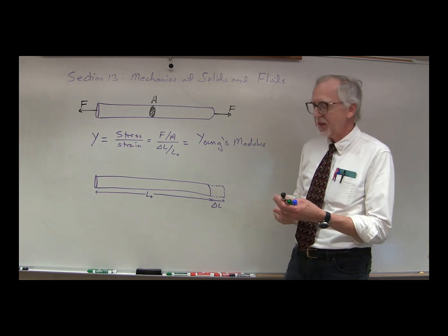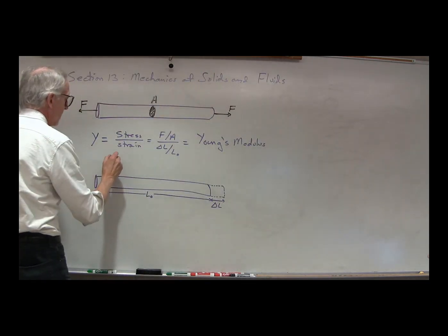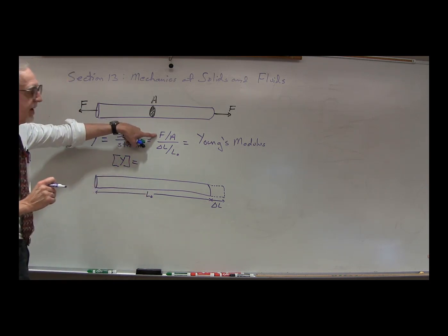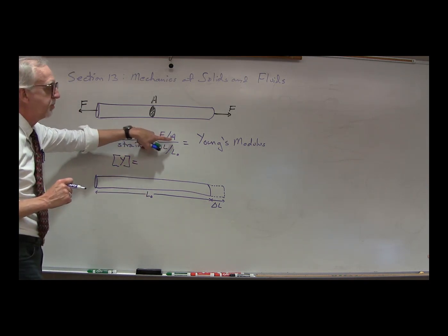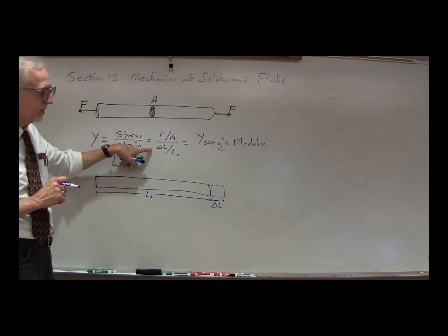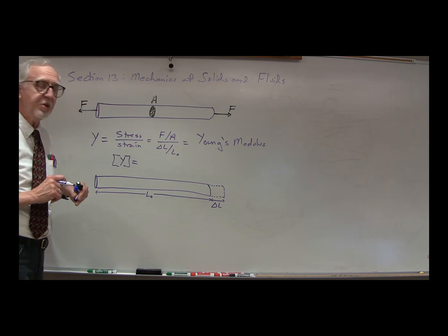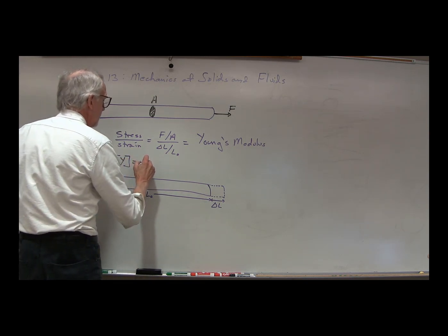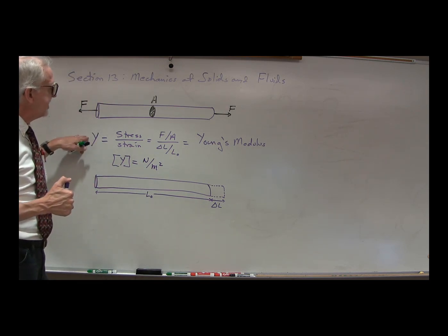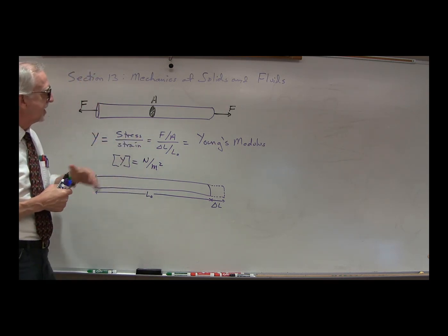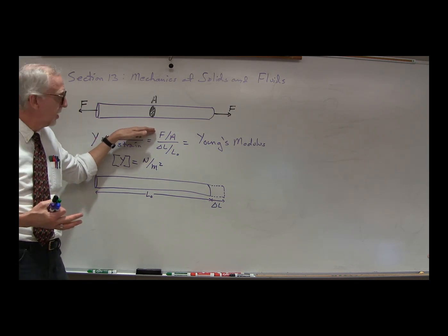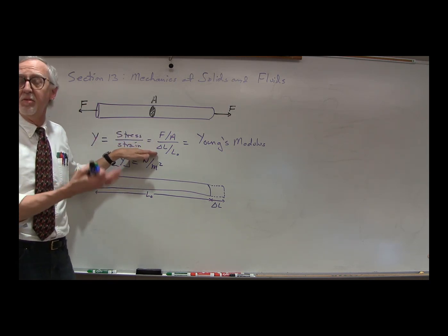What are the units of the Young's modulus? Well, that'll be the units of the stress. The units of the stress we saw were newtons per meter squared, divided by the units of the strain, and strain is unitless, so Young's modulus will have the same units as the stress, newtons per meter squared. So what is this telling us? It's basically telling us how much stress we would have to apply to an object per strain of 1.